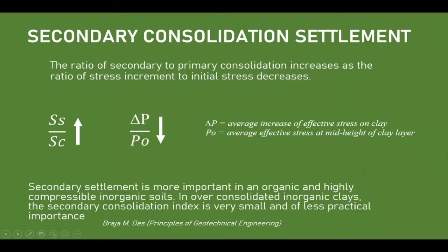According to Braja M. Das, secondary settlement is more important in organic, highly compressible inorganic soils. In over-consolidated inorganic clays, the secondary consolidation index is very small and of less practical importance. So if the soil is over-consolidated, or the PO is less than the past effective stress, the secondary consolidation index, or the slope of the loading curve, becomes smaller, and that's why secondary consolidation settlement is neglected if the soil is over-consolidated.